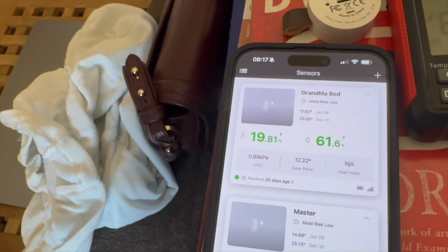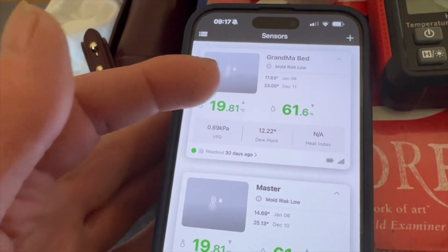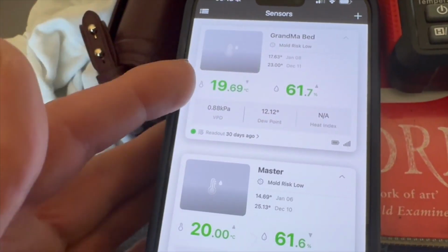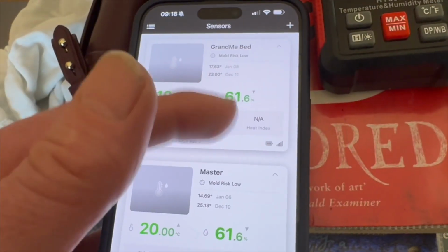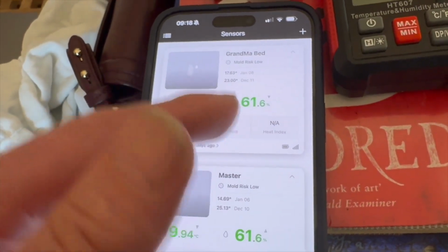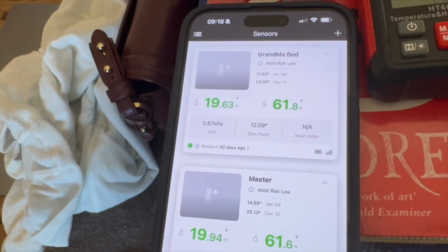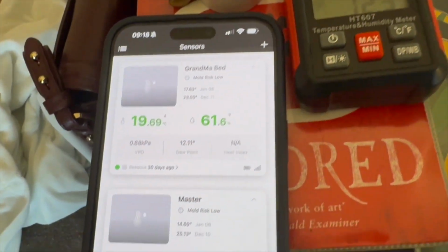And mold will grow where it goes above 85%. So that's why you're getting it. It's a combination of excess vapor, and we'll talk about that in a sec, and temperature. You should always deal with the excess vapor first, but then the temperature. The temperature is from insulation, airflow, and obviously heat from the radiators.